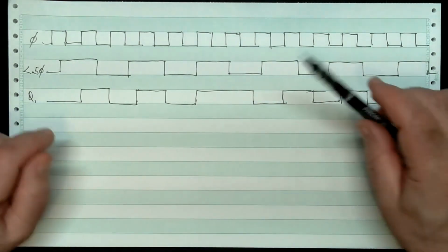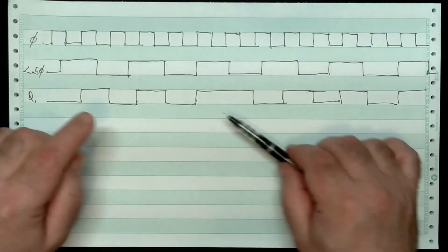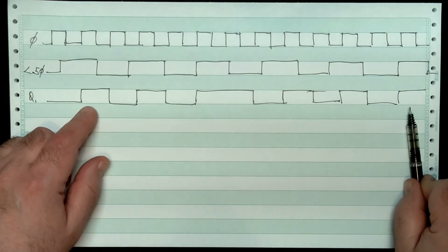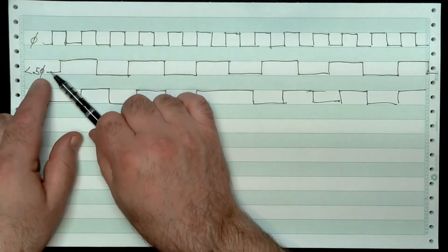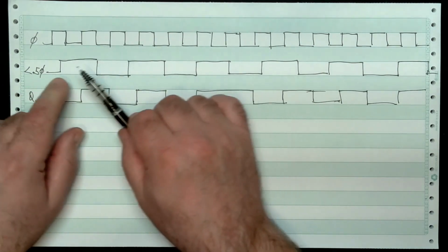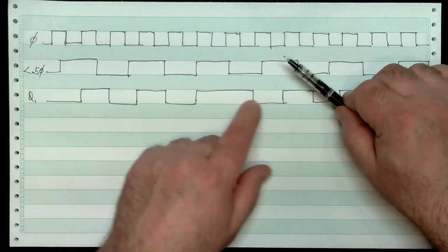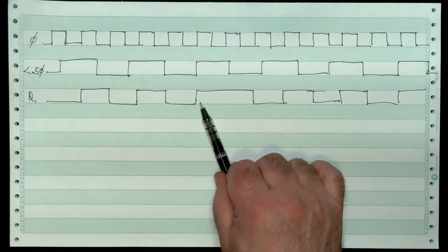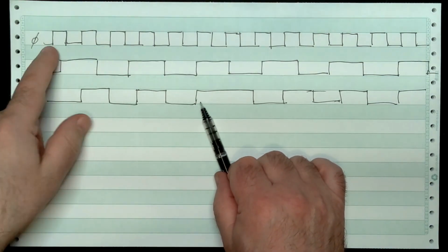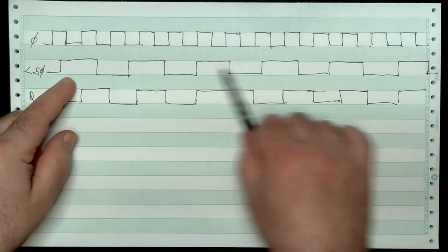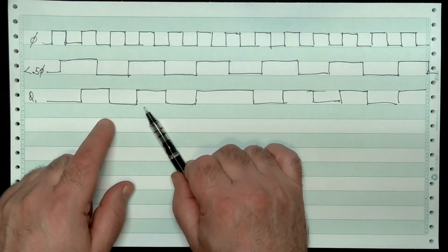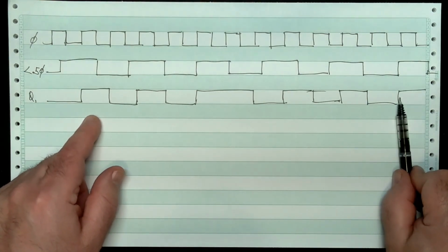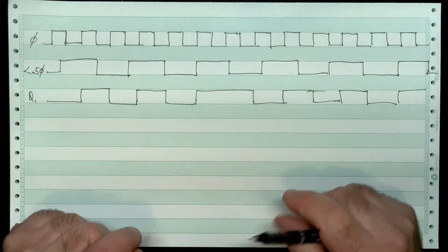So what you see here is the same number of pulses over the course of time that we see up here, which is the clock trigger input to the CTC, right? 1, 2, 3, 4, 5, 6, right? But this down here is synchronized to phi. This here is not. So is this okay? Well, in the long run, it's the same frequency, okay?